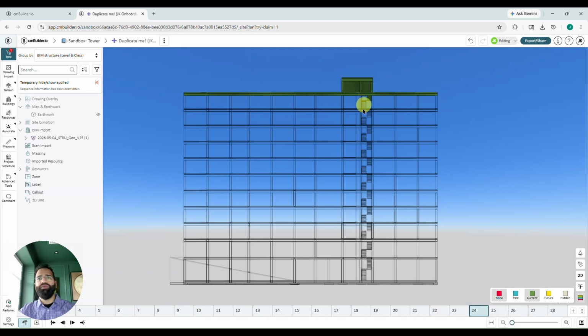You may have noticed I wasn't super careful with my stairs and stair landings. I selected sometimes the stairs from the previous level or the next level and attached them to the wrong milestone. Now those are a little bit tricky to select because they span multiple levels. They're also kind of small and hidden behind some walls. So we're going to show you another method to select just those stairs. We're going to use our scenario tree search to help with this.